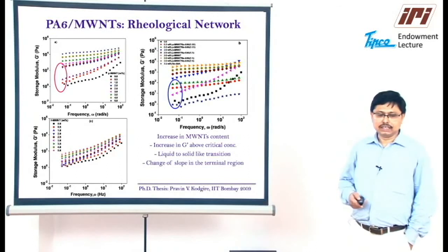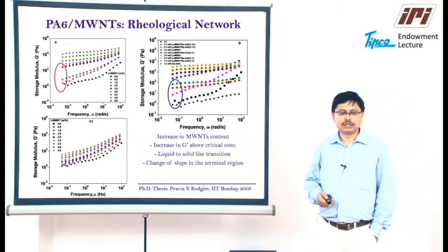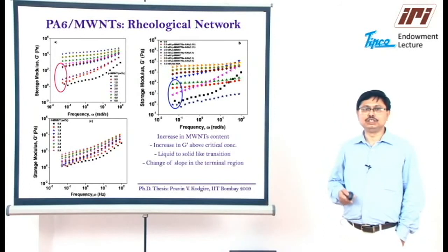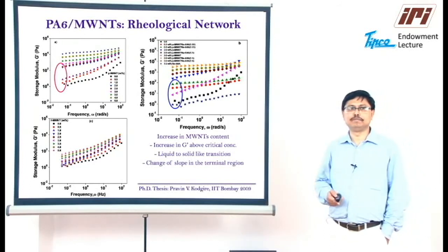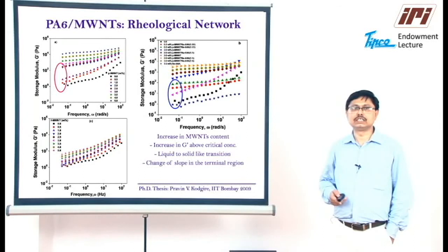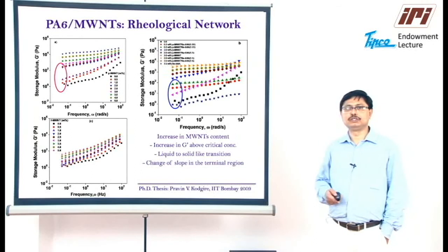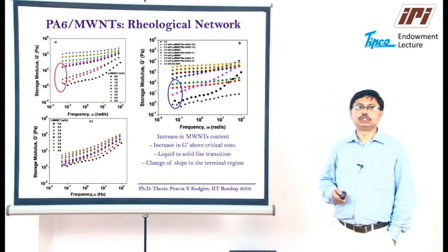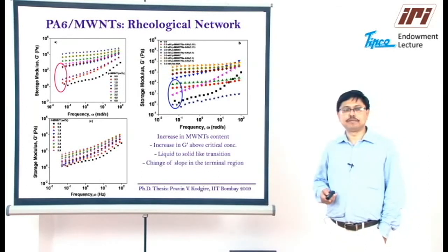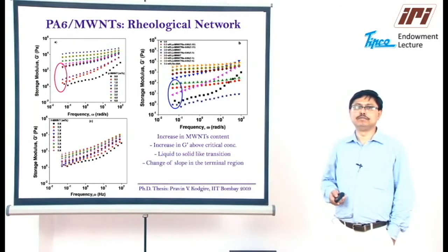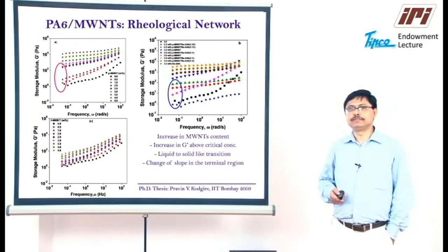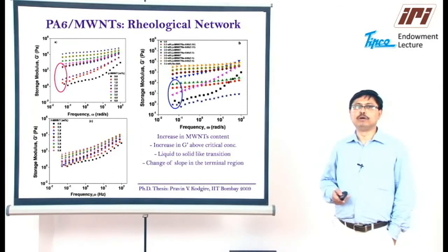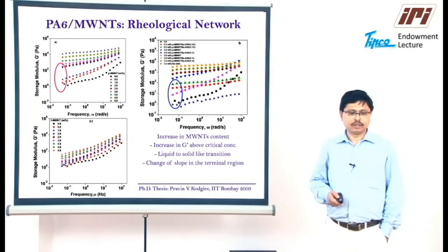The observation is similar in all these materials, and has also been observed in polycarbonate based multi-wall carbon nanotube composites: a transition from fluid-like to solid-like behavior is seen from the plateau of the storage modulus versus frequency plot, and in the complex viscosity versus frequency plot there is an increase in the slope at low frequency.